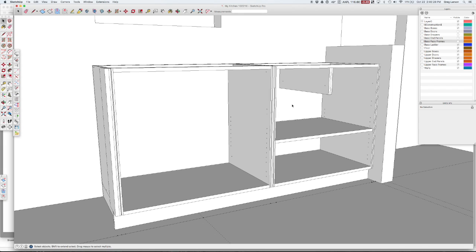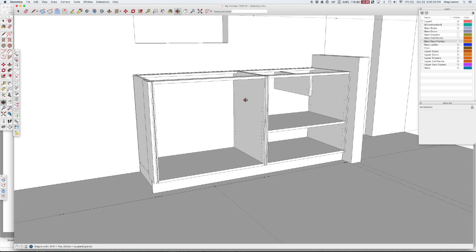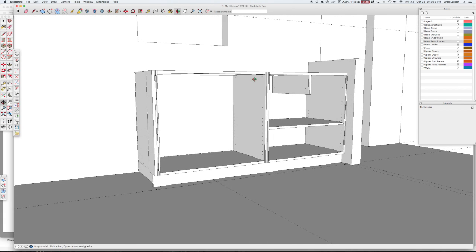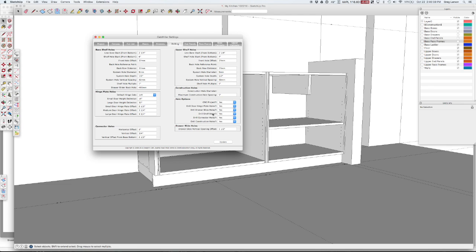And if you have a CNC, this will come out on the DXF files that you export, which we explain in another video. And they can be drilled all the way through precisely in the right spot on both of them. And you can use these 5mm connector barrel bolts that go through to connect your 2 cabinets together. Works really slick. So connector style automatically comes with those. So just beware, if you don't want those holes in there, you can turn that off. So if you go to your settings to drilling, we can drill connector holes, yes or no.